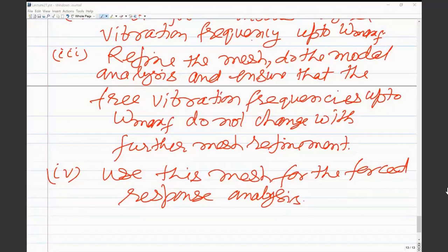Okay, sir. So FFT is not for continuous things. It is only for discrete things. If, let's say, the force is already a sinusoidal force, then you already know its frequency, and then you have to represent that many modes having natural frequency up to the forcing frequency correctly, and then use that mesh. And in the same way, you decide delta t.